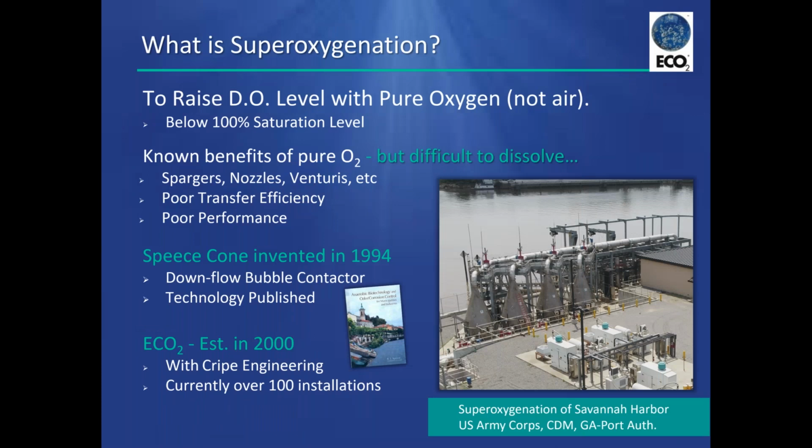So let's take a look at what ECO2 does. It's superoxygenation for the most part is what we're doing. And what that is, it's raising the dissolved oxygen level using pure oxygen, not air. And an important thing to note with this technology is that we're maintaining that oxygen dissolved level below saturation, below the 100% saturation. So we want to make sure that all of that oxygen stays dissolved and does not effervesce